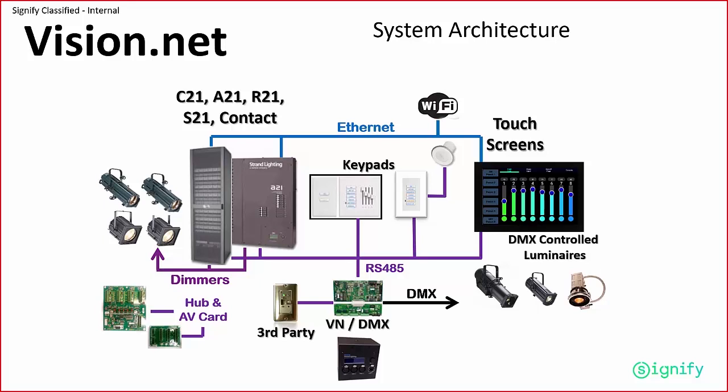So here we have a touchscreen over the RS-485 line. We are talking to keypads, button stations, slider stations, and wired directly to the keypad. They have input-output ports where you can attach sensors. So occupancy sensors and photocell sensors can connect into the system directly through the stations.